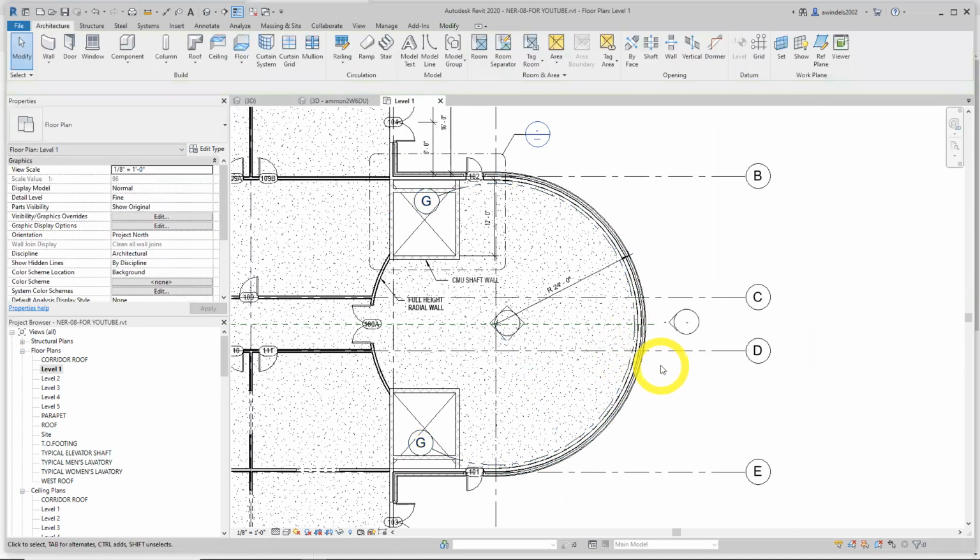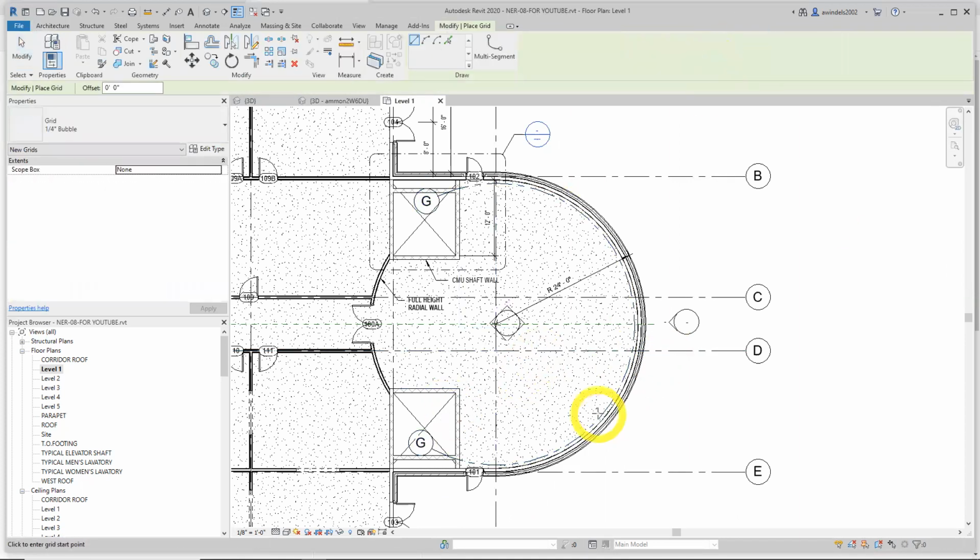as its constraint. We're going to add a couple more grid lines at 45-degree angles from the center of the radial wall to the outside. So we'll start at the center. So let's do that. And we're going to snap to the center of this radial wall, which sometimes is tricky, getting all the things to go to what you want. So we're going to type in SC for snap center, which is the icon I'm looking for. First point. And let's watch our blue. Wants to go to H, which is what we want. Let's say 45 degrees. It's lined up, good enough.